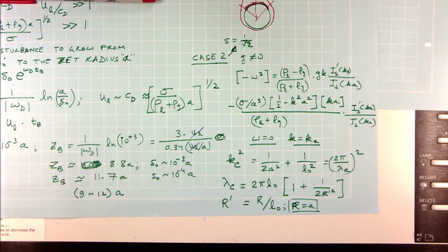That is the large heater, isn't it, where the heater size does not affect your heat flux, and there is a critical value below which the diameter of your heater starts affecting your heat flux, isn't it. Okay. So, let us figure that out. Actually, before I go there, let us finish the instability analysis, and then we will go into the large cylinder, small cylinder, large heater, small heater limit.